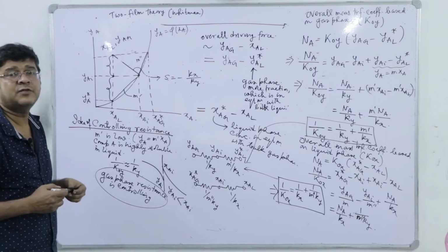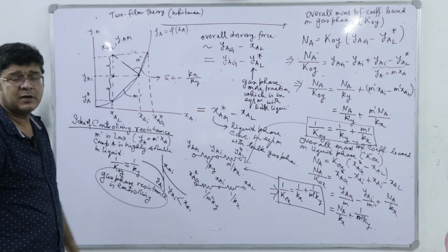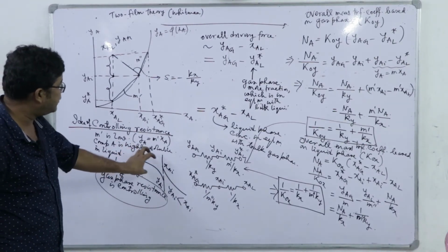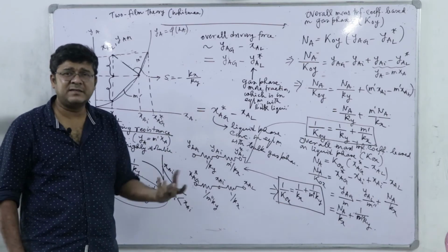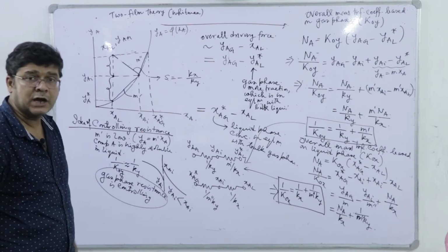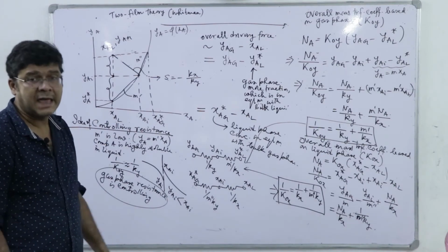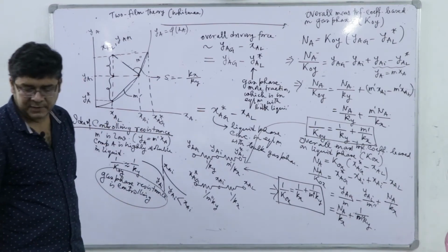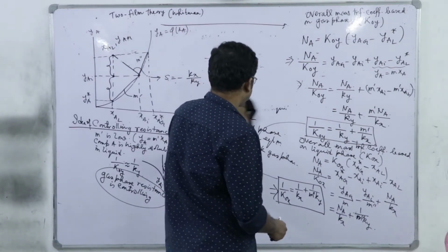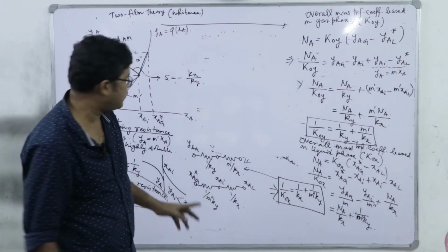And what does it mean by controlling resistance? Here you see that actually 1 by capital K or 1 by small k represents the resistance. So, this resistance is majorly contributing plus some additional very small or insignificant liquid phase resistance as the gas is highly soluble. But we are not focusing on individual values of Ky and Kx, we are only thinking in terms of m, right. So, this is gas phase controlling resistance. Alternatively, we can think of liquid phase controlling resistance from the same formula without changing the equation. We don't have to go for the second one, right.